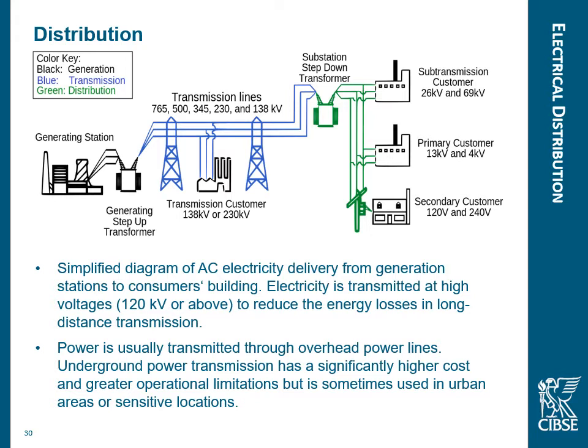Well, for distribution, 1,000 volts is quite low, mainly because of volt drop, which happens in the distribution system. So we need to transform that up. And in this country, we transform it up to around about 500,000 volts. We transport it at 500,000 volts, but of course we don't want it at 500,000 volts when it arrives at our building, and we transform it back down again.